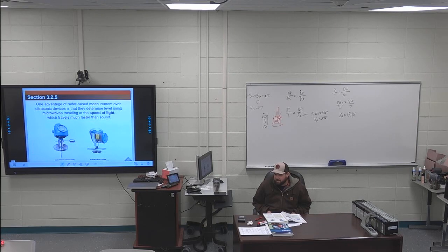Transducer. Yeah. So that's taking pressure in and outputting current, a 4 to 20 milliamp signal. Nice. But that's using, I don't have any highlights in head pressure, but think about it: the more pressure, the more water, the more liquid, the more whatever you put in a tank. It's going to put more and more pressure, and based on that pressure, we can determine a level.